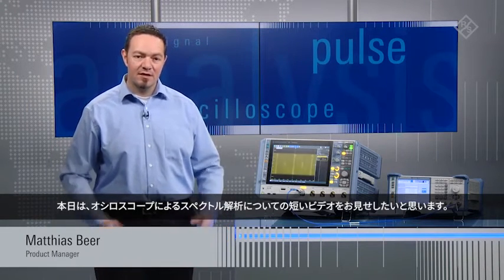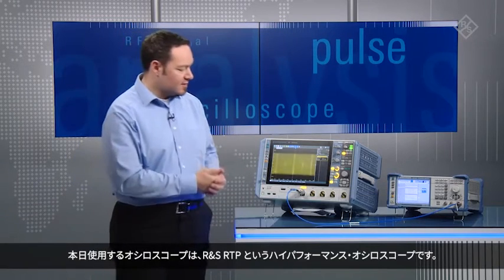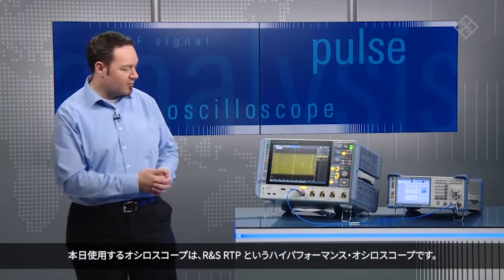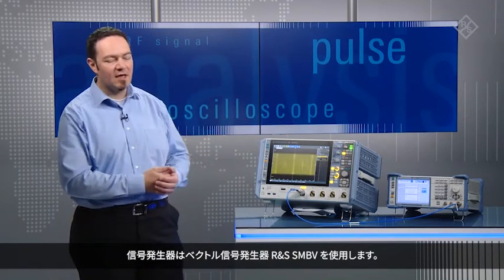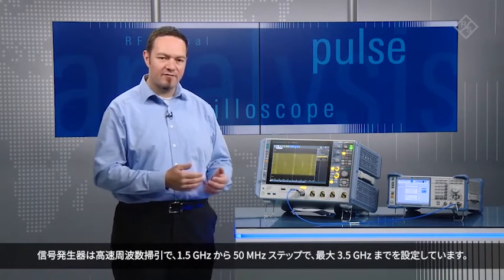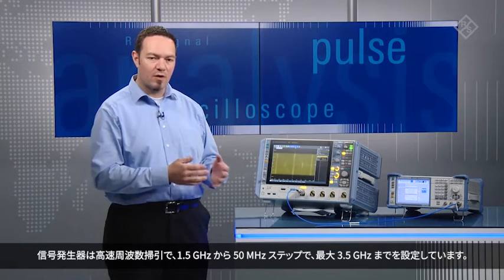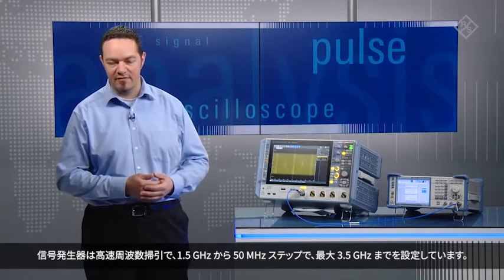Spectrum analysis using an oscilloscope. The oscilloscope we use today is our high-performance oscilloscope called RTP, and as signal source I use a vector signal generator, SMBV. On the signal generator I have set up a very fast frequency sweep starting at 1.5 GHz, going in 50 MHz steps up to 3.5 GHz.